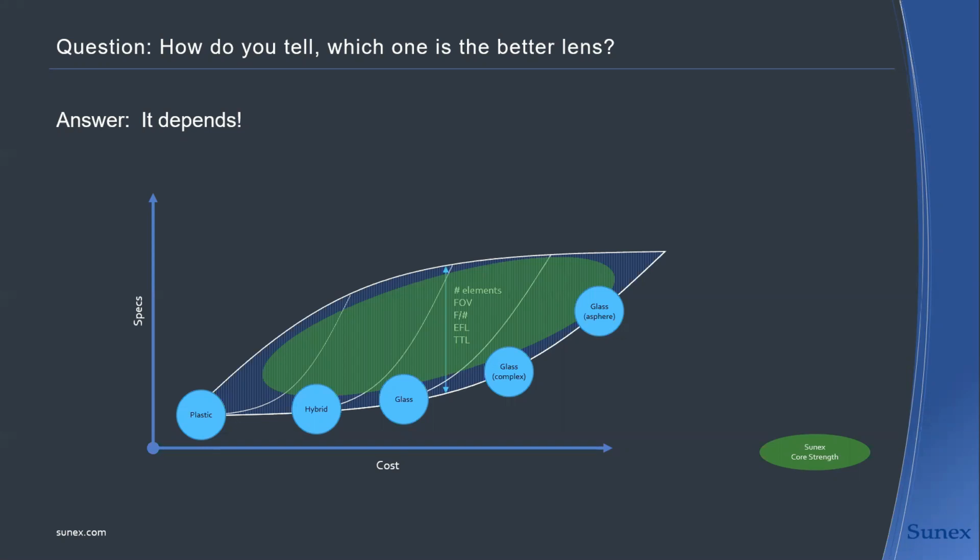Then maybe the first question for you, if you look at this surface area that I was showing here now, is the best lens always in the top right corner? No, not necessarily. As we have already discussed, best in air quotes is a relative thing, but in general, the best lens or the highest performance lens is really tied to performance more than it is material, and by extension, I think that can be related to the tolerances that are required. So an all plastic lens with very tight tolerances and very high performance may actually cost more than a glass lens or a glass asphere lens.